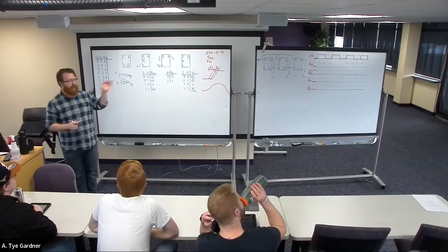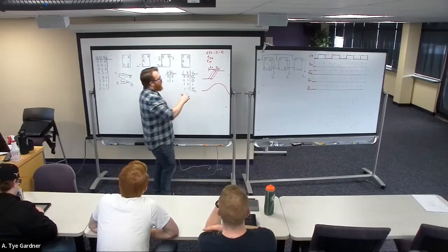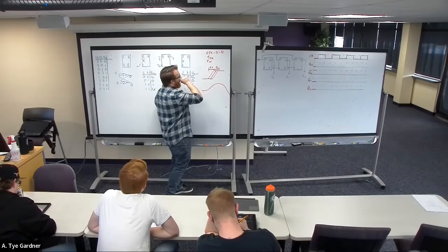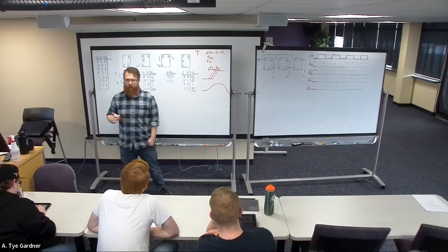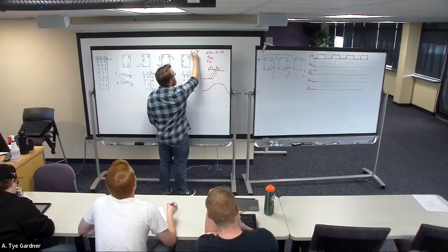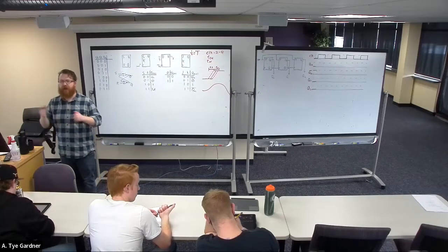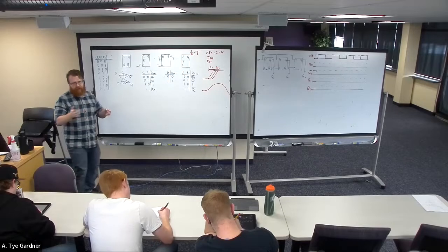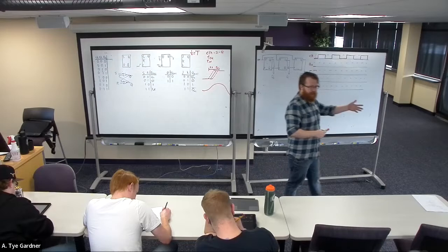If we start violating these timing requirements, it breaks. Okay, so the clock to Q, the little t is time. The clock to Q, a lot of times you're going to start seeing me reference it in terms of the period, capital T. Remembering that the period is equal to 1 divided by the frequency. Frequency being how often does a rising edge happen per second. How many times per second does a rising edge happen? That's the frequency of a clock. Or falling edge is the same thing, right? So that's what the capital T stands for, is the period of the clock.